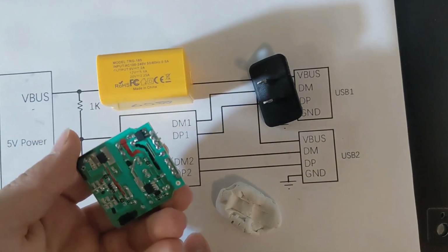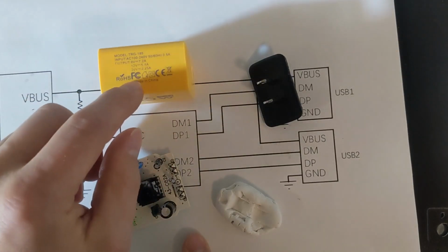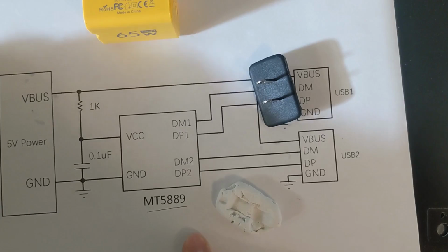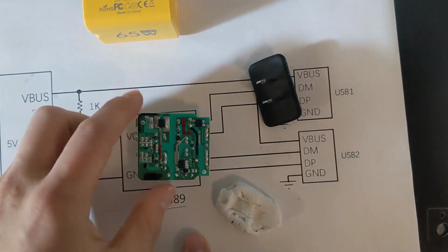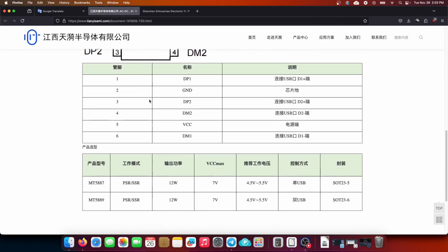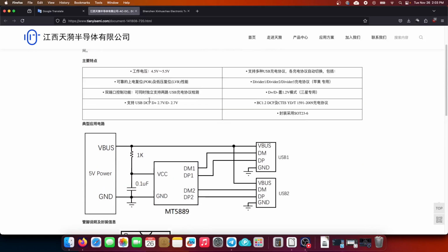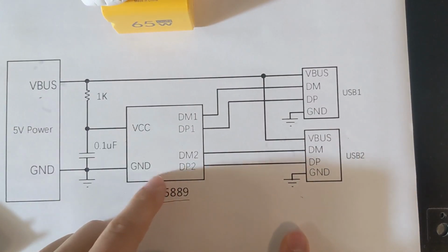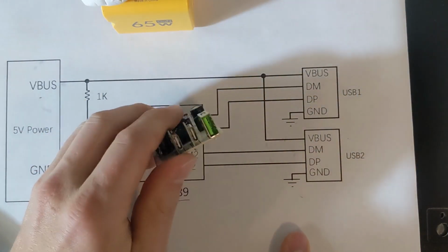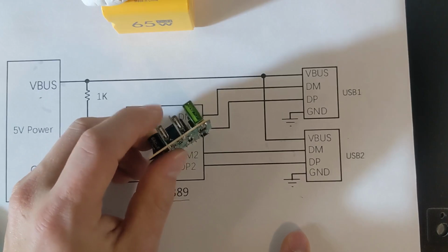And so when I looked at that, I was kind of surprised, because they say they got 20, 12, all this and that. Well, they also have this other chip on here, this negotiation chip, and we're going to get more into this later on, but it's called a quick charging chip, and all it does is negotiate with the phone or adapter, telling it, hey, by the way, this port can support more current. It can't support any more voltage.